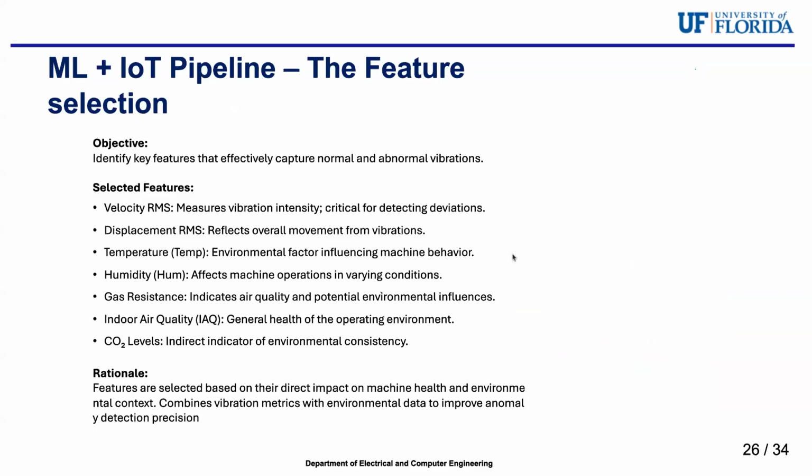Here I've just explained the overall sensor information data that we are utilizing. Just a recap again, but the catch is we have utilized velocity root mean square and displacement root mean square instead of acceleration data and gyroscope data, because there is supporting information defined by ISO for detecting vibrations. These two are the vital information required for processing these signals, so we could do effective predictions.